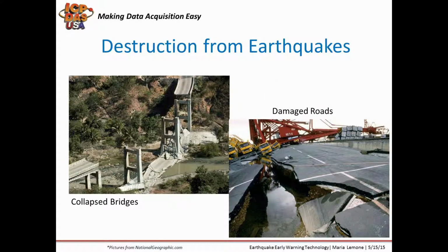Earthquakes happen suddenly and sometimes cause destruction, including fires, road and bridge damage, and collapsed buildings. Early earthquake warning technology helps prevent further damage, saves lives, shuts down critical systems as needed, and can help to alert personnel about seismic activity. An earthquake early warning system consists of accelerometers, communication equipment, computers, controllers, and alarms that can provide real-time notification about strong earthquakes that have potential for damage.